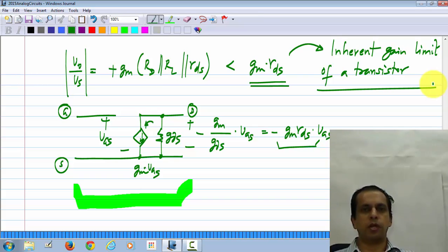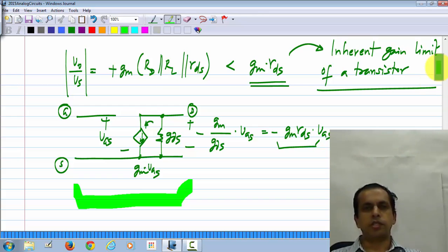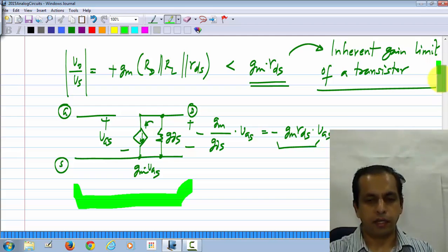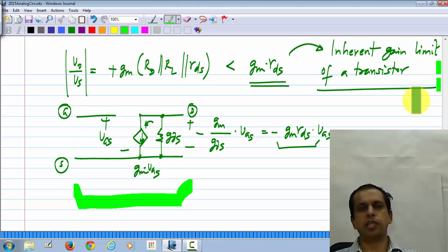So, for completeness, in MOS transistor small signal model, you have to include the output conductance. Now, because calculations are very cumbersome, we do not include it in the operating point and we do not include it for the calculation of GM and so on, although we could do it with some extra effort. So, unless otherwise mentioned, for operating point calculations and for GM calculations, omit the effect of lambda, but lambda will cause the MOS transistor to have an output conductance GDS, okay, and that you have to include into the small signal picture of the MOSFET in any circuit that you have, and of course, like GM, GDS also depends on the operating point, okay.